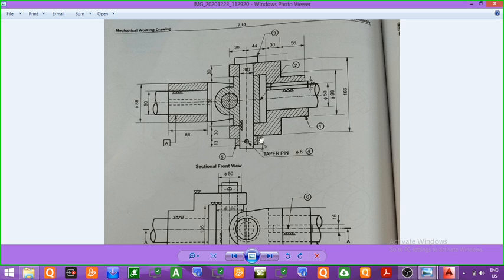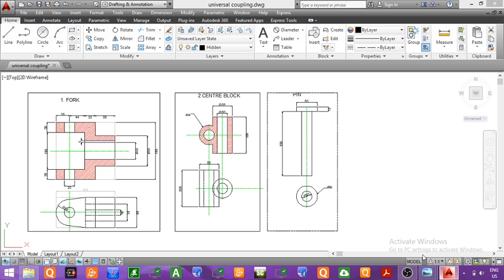So, for drawing this collar, we needed the height which was equal to 13 mm, the diameter equal to 50 mm, and the cylindrical hole inside the collar of diameter 30 mm. Also, the hole provided inside the collar for inserting the taper pin is of diameter 6 mm. So we have obtained all the dimensions related to the collar. Now we will draw the collar.